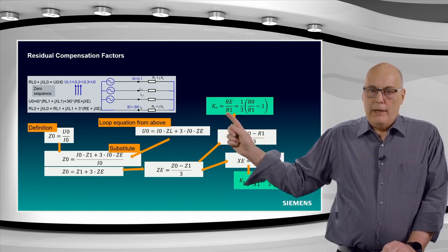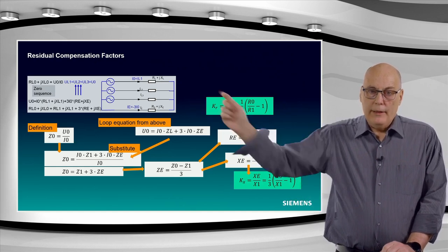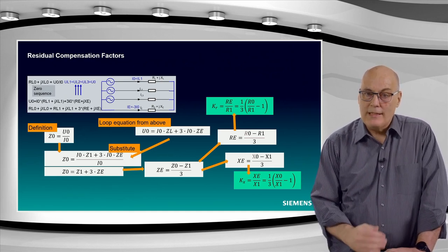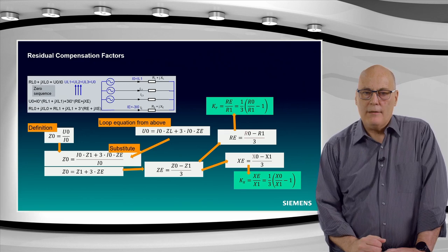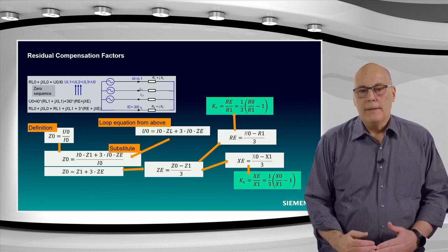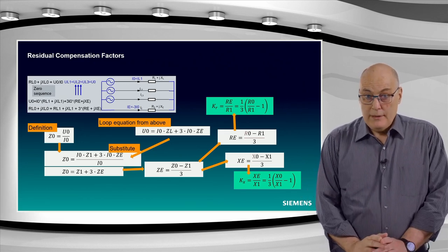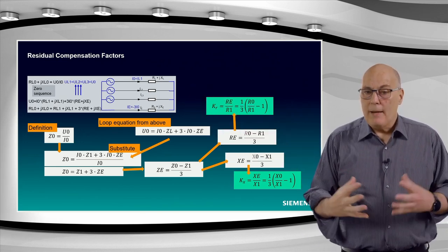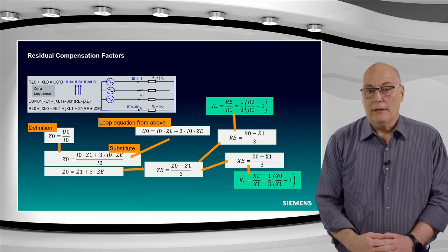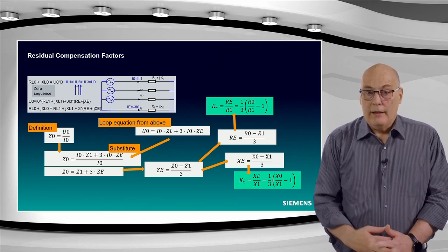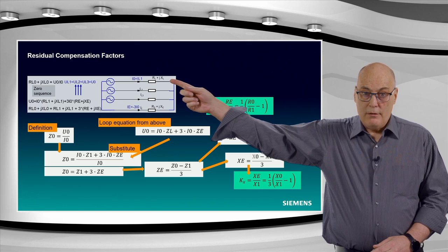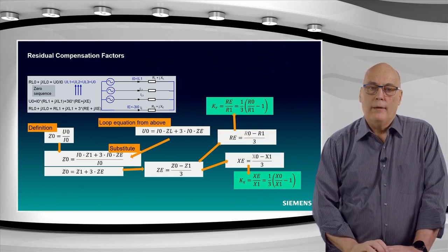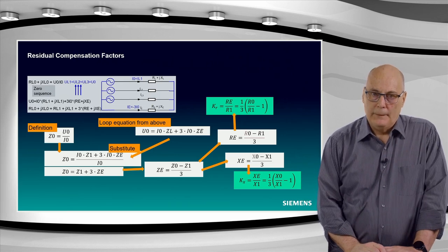Why can I replace R1 and RL? You see it in the diagram here. You see that the impedance, as it is shown in the three phases there, is the ZL, which is RL plus jXL. That is your positive sequence impedance. For it to be a positive sequence impedance, our assumption is that those three phase impedances are exactly the same and balanced. That's the definition of a positive sequence impedance, and that then can be substituted directly. So we can replace that RL, XL in this case exactly by the positive sequence R1 plus jX1, the definition.